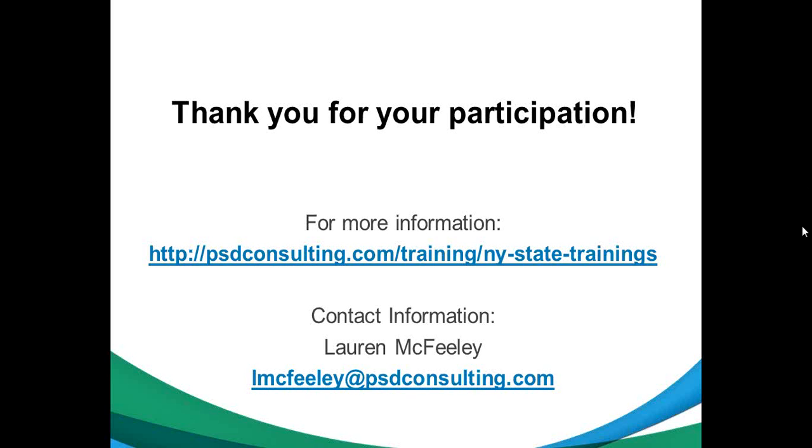And typically you want to do this at different times of the year. The shoulder seasons between heating and cooling are a great time to catch things like, is the economizer working properly or not? You'd like to do it in the summertime to catch the chiller operation, the wintertime to catch the boiler operations. But sometimes you can get lucky and the shoulder season could catch everything. You might be able to catch issues with the chiller and the boiler in the shoulder seasons. Looks like we had a couple more questions.